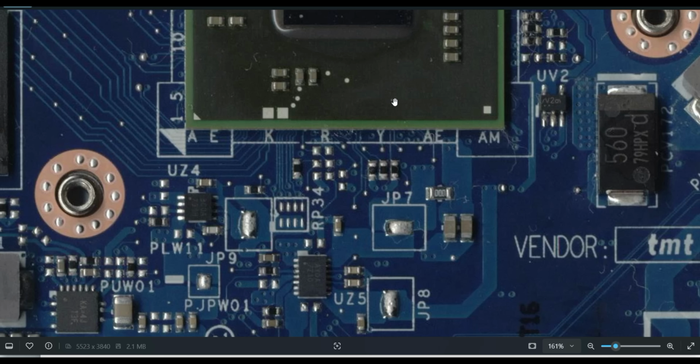But if the IC is taking it as an input, then the problem is with this component, the I2C component. In that case, we will consider the I2C component faulty or maybe the resistor faulty. Then you need to open this path and check the destination part, whether you are getting 3 volts or 2.8 volts. Otherwise the component is faulty.